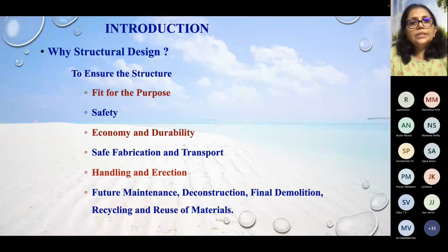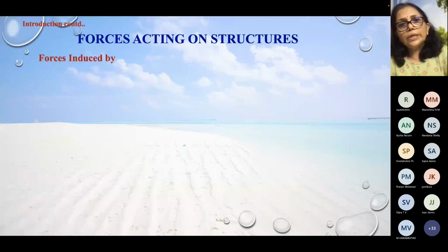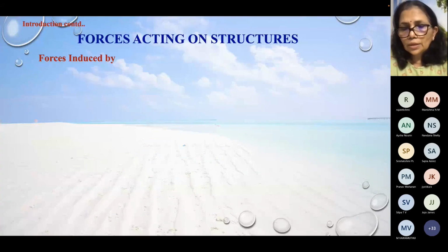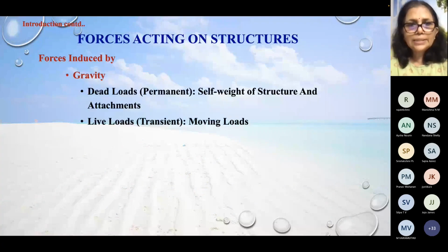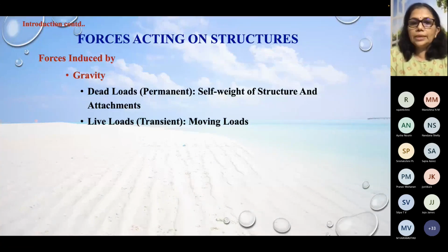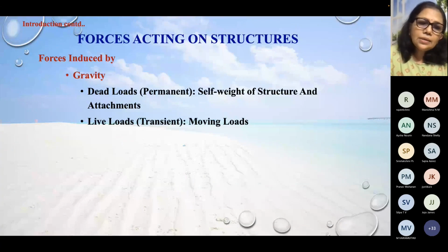And this is required for design. So when you have to design, you should also know what are the forces acting on the structure. So what are the forces acting on the structure? The forces induced by gravity are there. So the gravity loads are the dead loads, which are permanent in nature, which means they are the self weight, and some attachments which are permanent in nature.